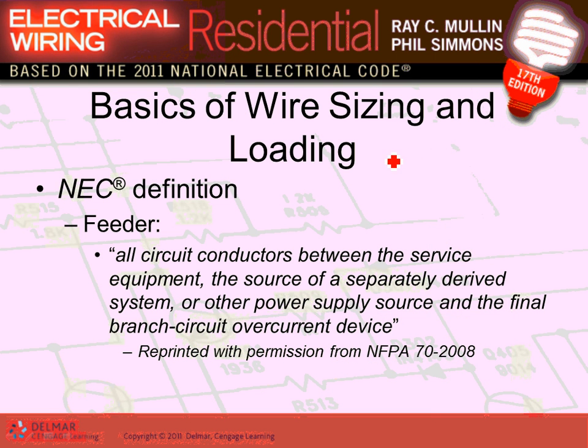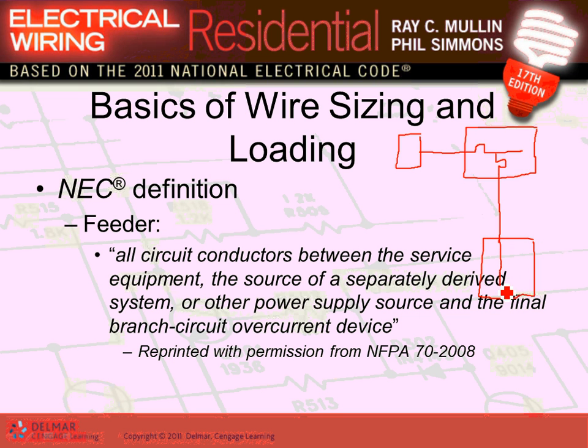So, here's the transformer coming from the electrical utility. You bring it to your building. You put a circuit breaker here. Here's my main panel. Out of my main panel, I took another circuit breaker and put it in another panel. Look how it goes. And out of this panel, which is main lugs only, I took a circuit breaker and I fed my light. I'm lighting just a light here, or a motor or whatever.